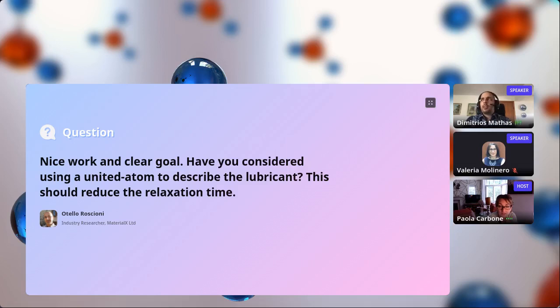Yeah, I'm aware there is the Einstein relation for viscosity as well. We didn't try this equation. We used Green-Kubo in the first place, which was implemented in LAMMPS. Although, I then rewrote the autocorrelation code with an in-house C code to experiment with the convergence and the different autocorrelation parameters. But yes, this is another equation.